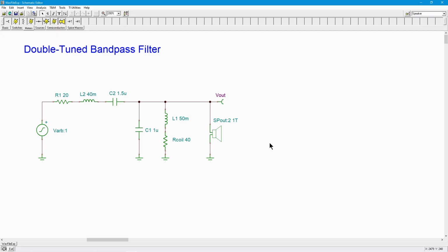Great. Okay, so extremely useful, I think, if you're doing any kind of audio work, because now you have this cycle where you can listen, tweak, listen, tweak, listen, tweak, right? And get things where you want a lot faster than doing it on a breadboard. Ultimately, of course, when you're done with all that, you do like to breadboard things to get the final sort of ear check, right? Plug in a proper instrument, play. You can fool around with dynamics and phrasing and stuff like that and see if the circuit's working the way you expect it to.